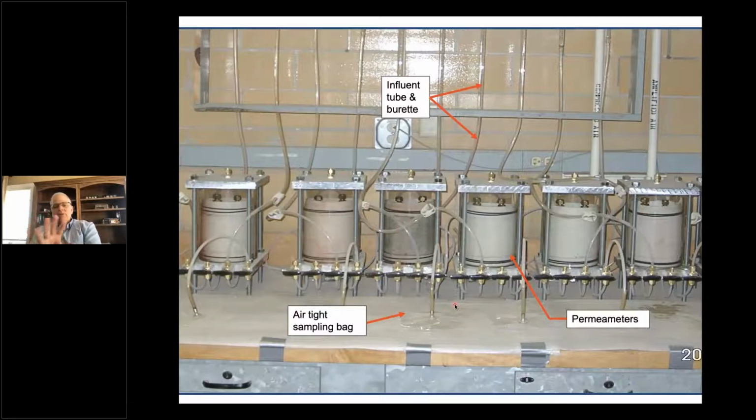One of the attributes of this I said I would mention is part one, I'm not using air pressure at all to induce elevated pressures in my specimen. So the pressures that are being applied, particularly the water pressures, are typical of what that GCL would see in the ground. And for just looking at hydraulic problems, probably not important. But when we change the pressure on the liquid, we potentially may change the geochemical interactions as well. And so we would like to use low pressure systems if we can when evaluating chemical interactions between leachates and GCLs so that we do not alter one, the chemistry of that leachate, or two, the interaction of that leachate with the solid surface in the bentonite.